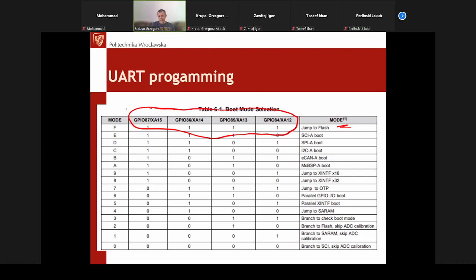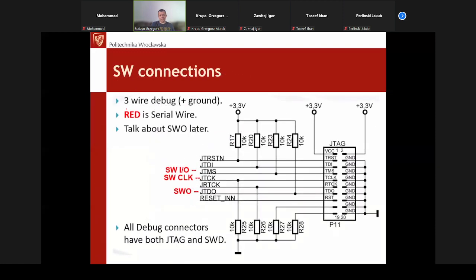But again, sometimes it's a pitfall, especially if on those pins there is a dedicated SPI or UART or whatever interface that we intend to use later on during the functioning of the device, and during reset it has to be configured strictly to 111, for example. Anyway, this table has to be found and analyzed.